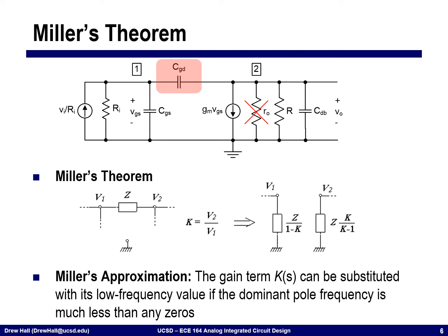And so simply put, what we're saying is that if we were to look at a pole zero plot here and have several poles and several zeros on this plot, using Miller's theorem, I can precisely figure out what this dominant pole is, that is the lowest frequency pole, but I can't do anything about any of the higher order poles and zeros because after I hit this pole, this gain expression is going down.